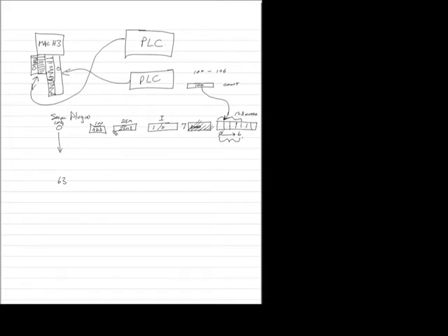You could, for example, have configuration 0 set up to transfer those 7 words at a 25 millisecond interval. We could then say that on configuration number 1, that we want to start at address 107. We want to transfer every 100 milliseconds input, and we want to transfer 5 registers.